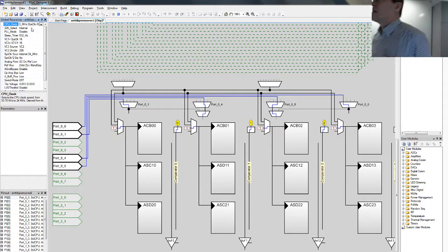It also has an internal 32K, big K, so 2 to the power of 15 hertz, meaning that you can put a simple 16-bit divider on it to get a 1 hertz clock rate.